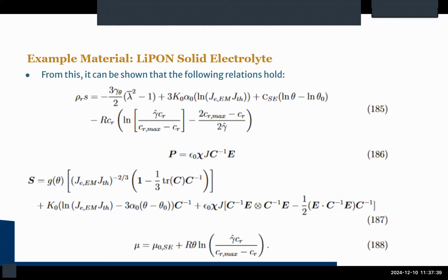You get an entropy expression, you get a stress expression where the dependencies on the thermal part and the electric field are evident. There is an electric field dependency in the stress here. And it is such that it cancels the part that is determined by the polarization in the Maxwell stress. The Maxwell stress is a stress tensor that owes itself to electromagnetism being a part of a system, and it's not a part of the, or in this case, second Piola-Kirchhoff stress tensor. So you end up adding those two together in the end, and what you get is like the total effective stress tensor. So the electric part here cancels out the polarization part, making this into a material that is not a piezoelectric. So the total effect of the Maxwell stress on the material ends up being due to the free charge alone. And then you get the chemical potential that is expected from the literature out of this function for this material.